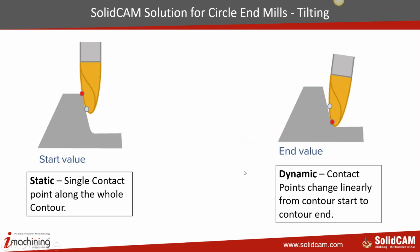So you have again here the static mode, where you have a single contact point. This contact point will always remain the same, so even when the tool comes here, the contact point will be the same. It will stop the tool path, so your tool path will be only up to this area. Anything beyond this, you now need to change. If you move to the dynamic mode, it will start with this contact point. However, it will end with the contact point at the bottom, thereby it will be able to machine the entire surface right up to the fillet. Both these modes are now available to the user.